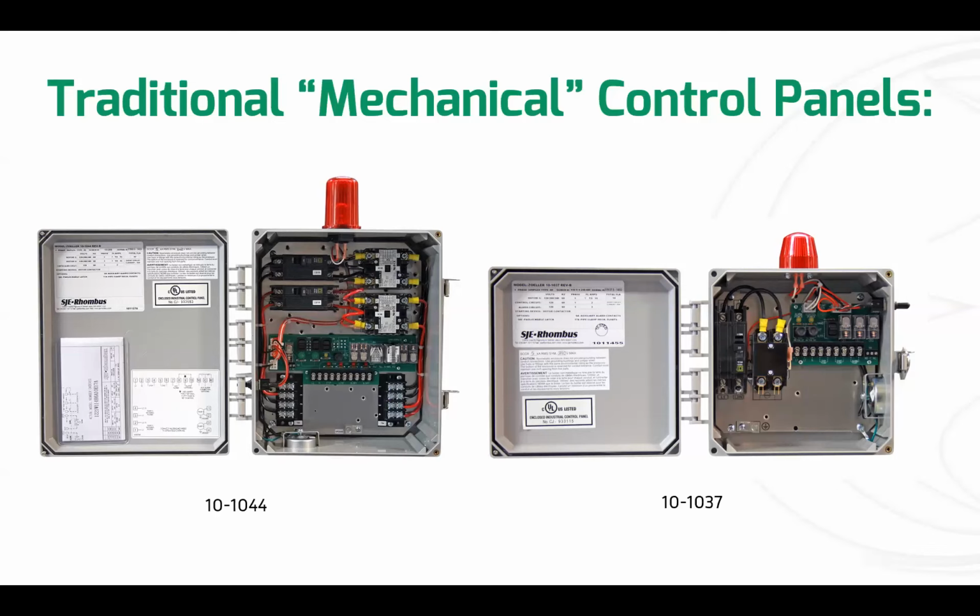It's got an HOA or hand-off auto. It has inputs for float switches and power, outputs for pumps. There's a dry contact pretty much on any panel made. So this is a typical panel. Now, if single phase duplex, no features is what you want, then that one on the left there, that was our old part number, that's going to be sufficient.